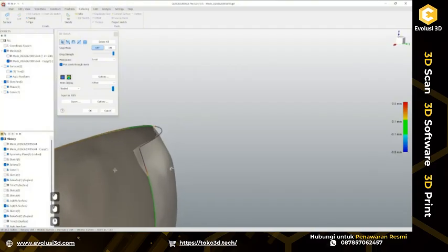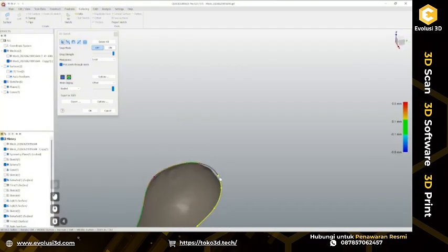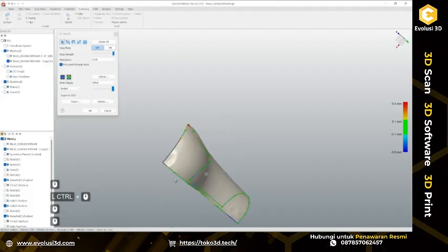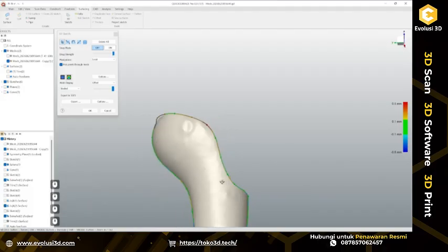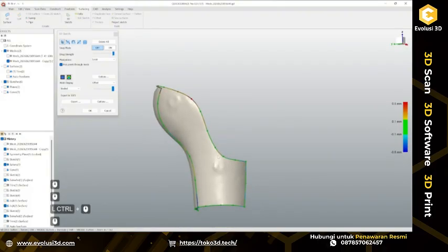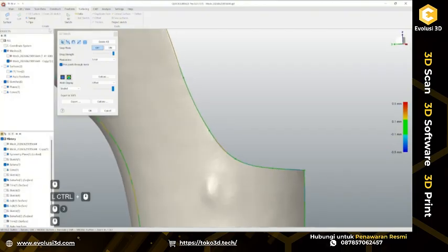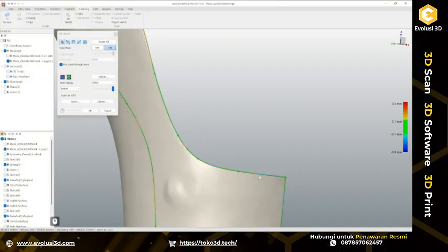Let's just pull it something like this. So we have more or less a nice and smooth flow of this 3D curve. Okay, so here I can enable my snapping and move around this control point to get closer here on the edge, probably this one.